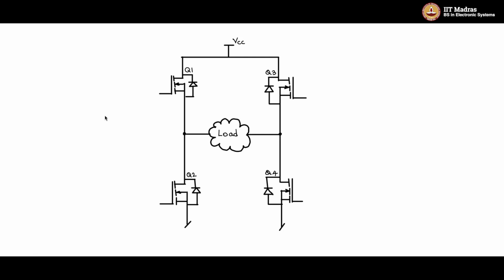So we know that we can give a sine wave as the modulating signal, compare it with a triangular wave and get a PWM signal. Let me draw that for you here. So I am having the y-axis and the time axis here, and the y-axis will give you the signal amplitudes. So let me take a sinusoidal profile like this.